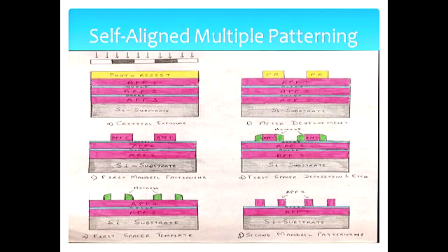If we understand correctly, you have the ability to selectively remove either the nitride or the oxide, so you keep alternating between nitride and oxide, etc. That is another method of doing it. But again, like I said, spacers are not very robust. Mandrels are what's more robust in maintaining the critical dimension. Mandrels will give me a very good edge, while the spacer will not. If I alternate silicon nitride and oxide, it will only be spacer deposition. That will not give a very good line critical dimension, or it will not be as accurate as it will be with mandrels.